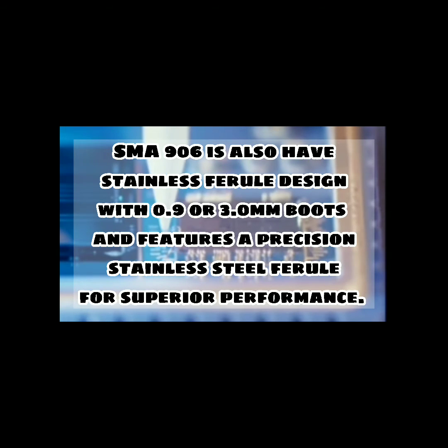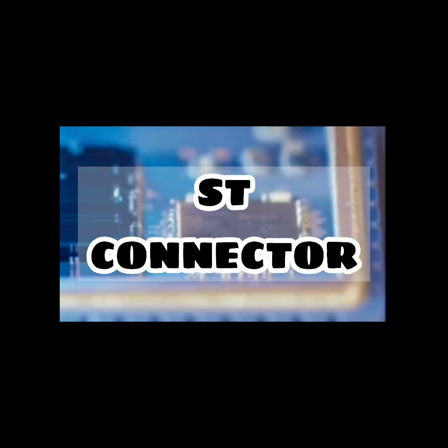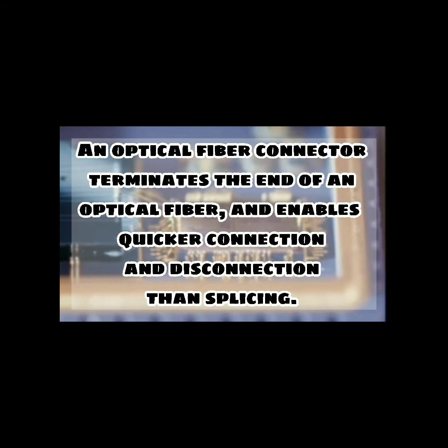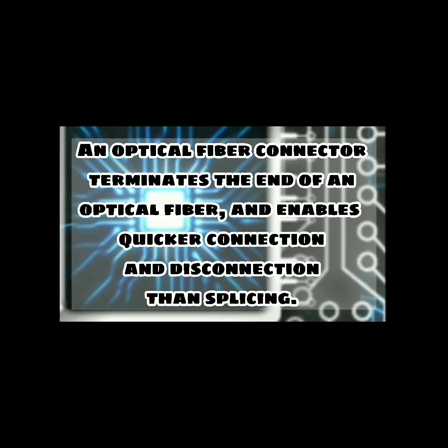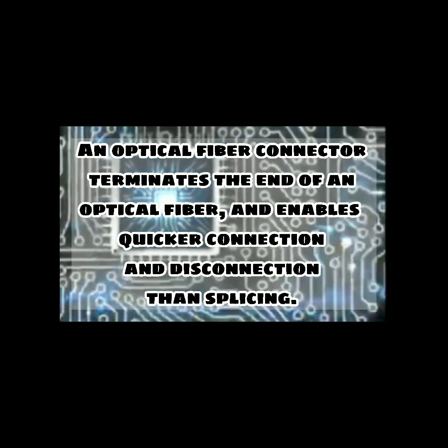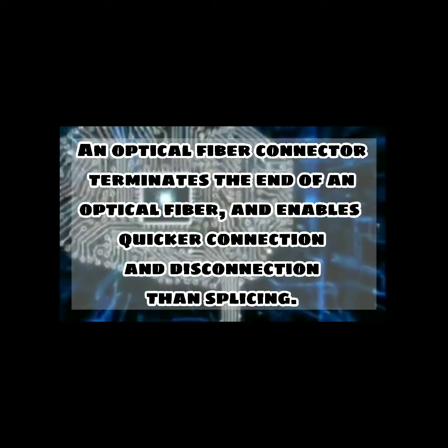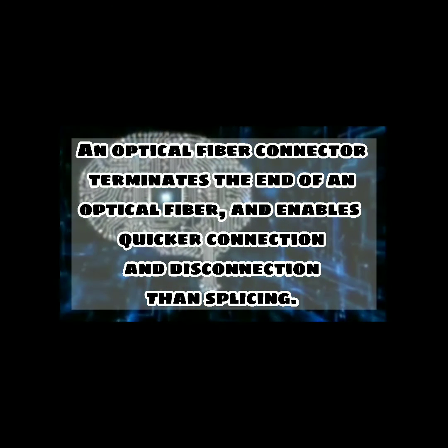SMA 906 also has a stainless ferrule design with 0.9 or 3.0 mm boots and features a precision stainless steel ferrule for superior performance. Next is the ST connector. An optical fiber connector terminates the end of an optical fiber and enables quicker connection and disconnection than splicing.